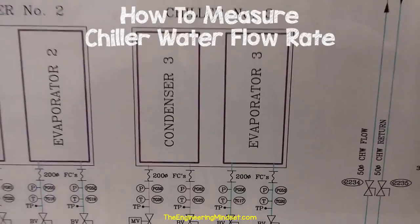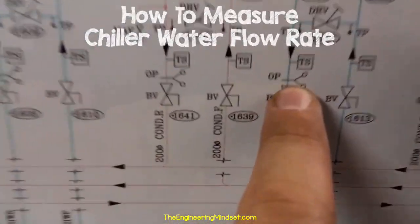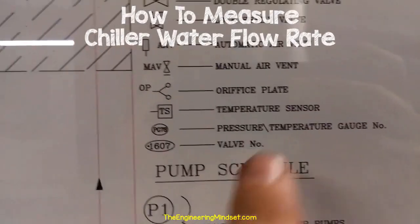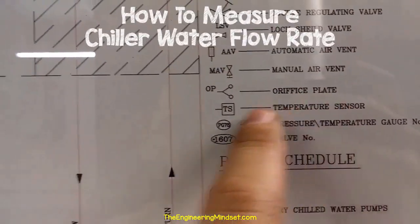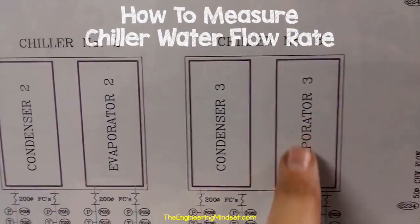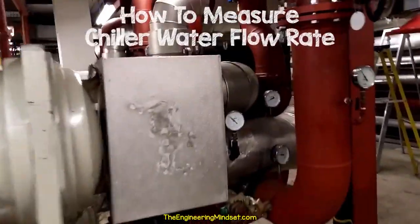First we need to find a point in the system that we want to know what the flow rate is. For this we will use this orifice plate here on the chilled water flow pipe coming out of the chiller. We can just check on the drawing legend that this is an orifice plate, which means that we can measure here. So we need to find the evaporator for chiller number 3, which is this one here. Then we follow the pipework until we find the orifice plate, which was just after the bypass valve, and there it is.